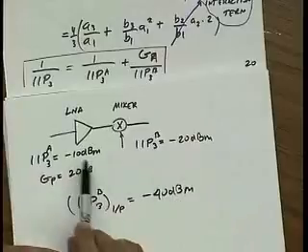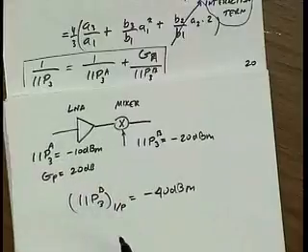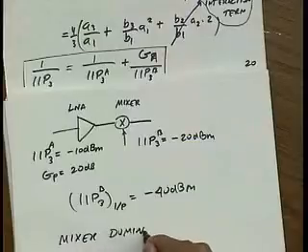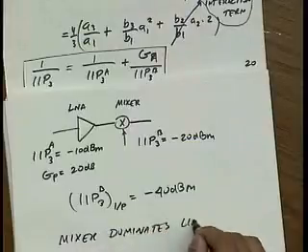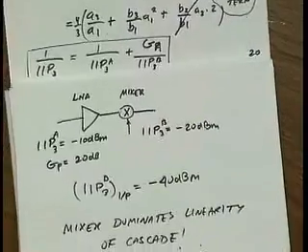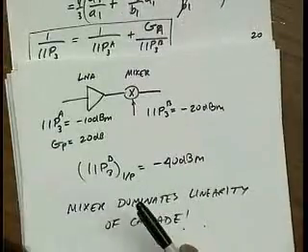So it's 10,000 times smaller than the IP3 of the input stage. So clearly, the mixer will dominate the linearity. There's no need to even use that formula because one term is 10,000 times bigger than the other term.